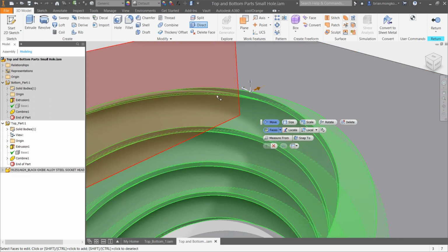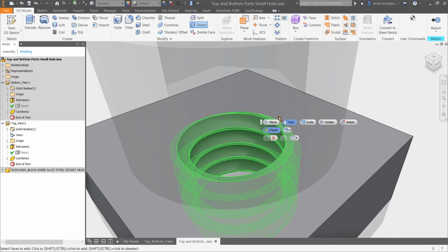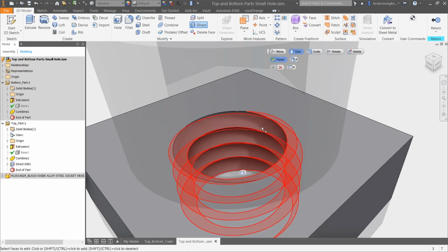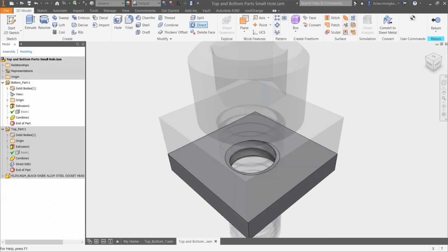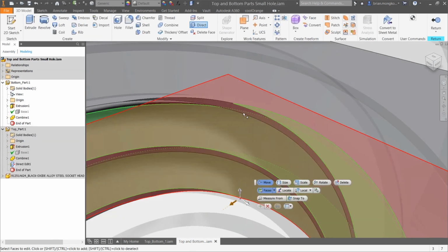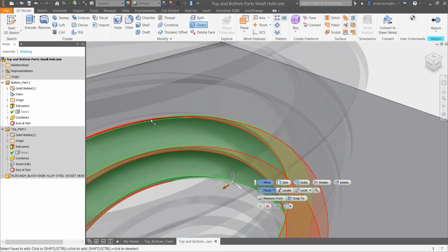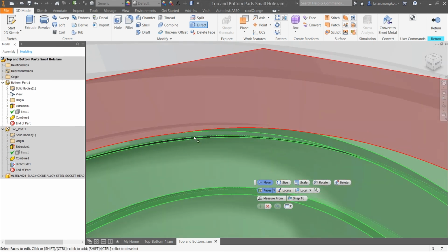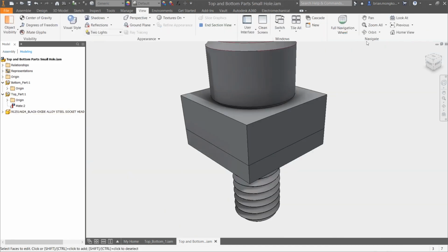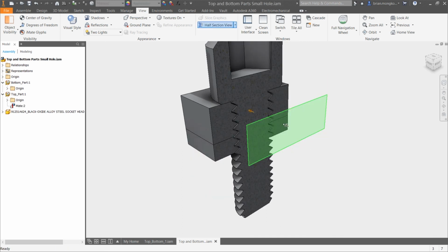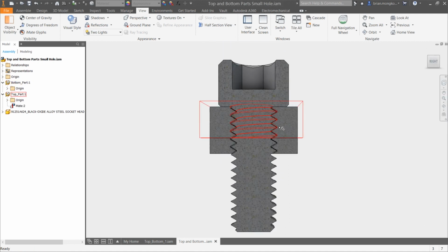Select the 4 faces there. Change the size. Use the 5/1000ths of an inch to make it just 5/1000ths of an inch bigger. Good with that. We'll edit the bottom. Direct. 1, 2, 3, and 4 faces. Change the size. And now we have, hopefully, the threaded holes using the Boolean operation.